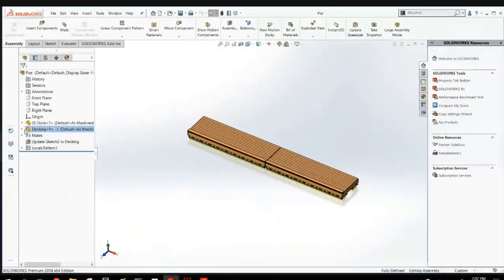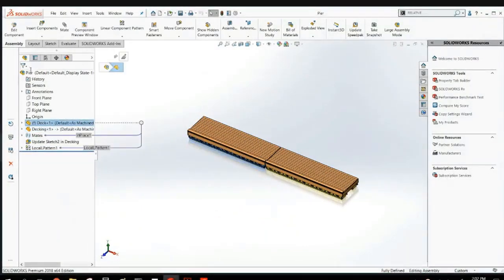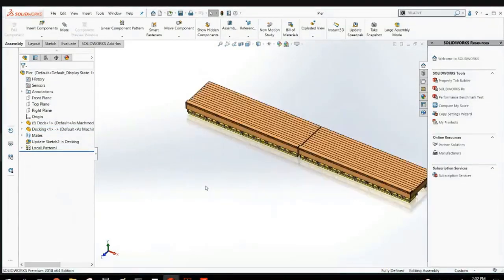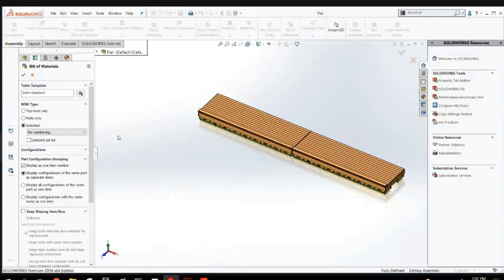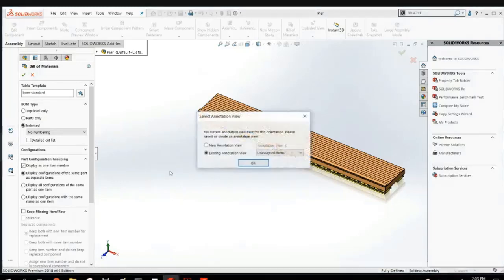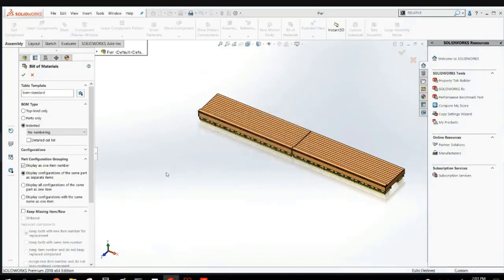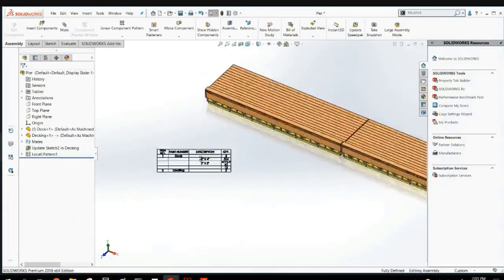When you have a sub-assembly, so this is an assembly that includes weldments, and you do a bill of materials with an indented list, it has to be an indented list, the part has to have weldments underneath it for this trick to work. But if I create that bill of materials, I'm just going to drop it in at the assembly level here.